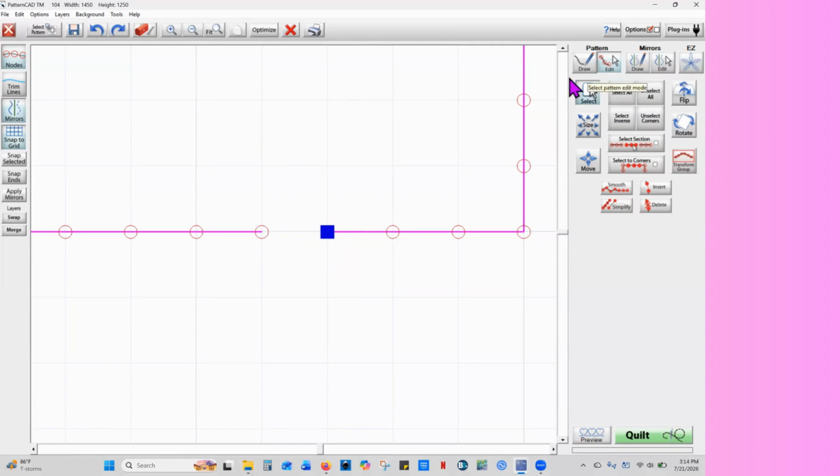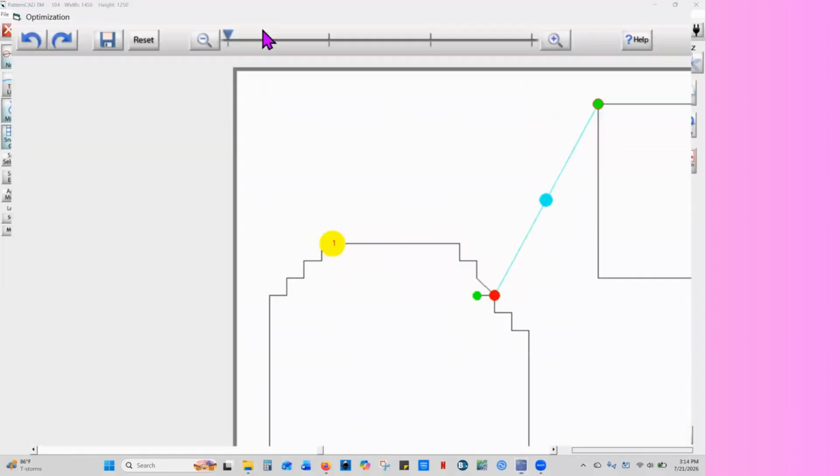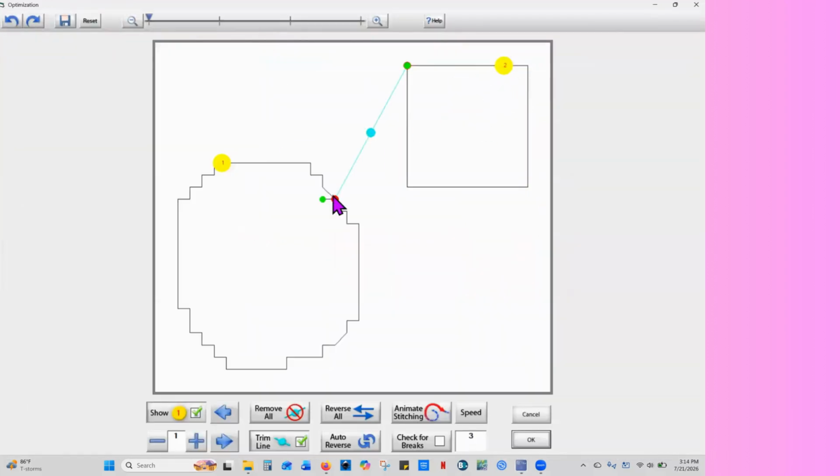I'm going to say unselect everything. I'm just going to join this by selecting this node. I'm just going to pull it over to that one. There we go. And so it wants to snap. It might have more than 1 line segment now. Let's look. The square does not, but we would have 2 line segments because they're not joined. That's what we would be expecting.